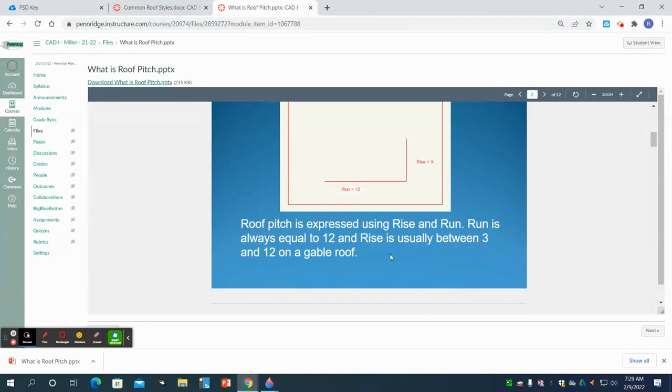So a friend of mine sometimes will call me and ask me to help him out on a roof. And I'll ask him two things. I'll say, what's the pitch and how many squares? If it's anything over a 6 pitch, at this point in my life, I don't really feel like working on it. They get too steep, it's too hard on my knees and too hard on my back. So I usually don't work on roofs that are any steeper than a 6 pitch anymore. When I ask how many squares, that just tells me how big the roof is. When they talk about a square on a roof, it's just a 10 by 10 foot square, and that usually takes 3 bundles of shingles to cover it. So that gives me a rough idea of how big the roof is and what the roof pitch is.